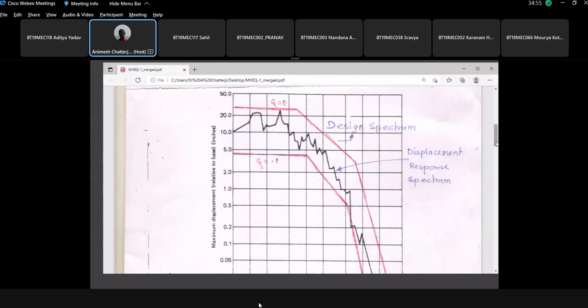Why? Their construction is different. The construction of village houses is solid wall and not column construction. What is the problem with column construction? What is the advantage? It uses less material and cement, so it becomes cheap, but its natural frequency decreases. So for an earthquake, a column-constructed house is more susceptible to damage than our typical village houses.